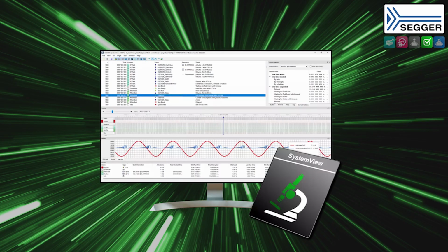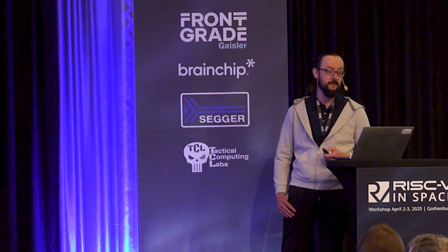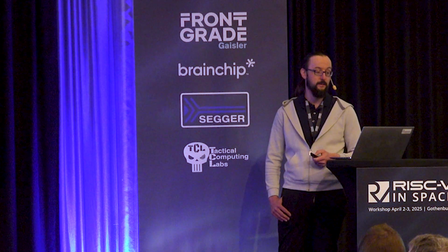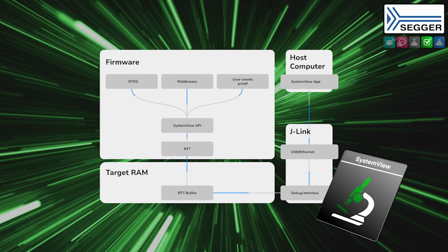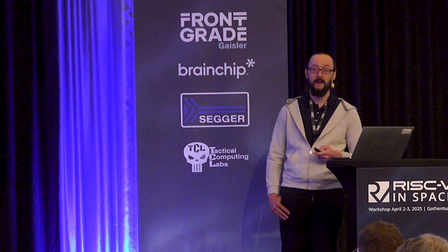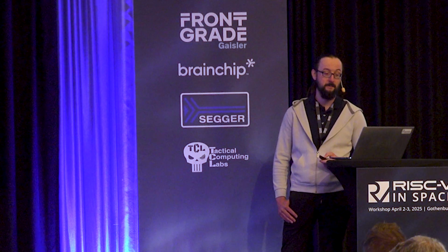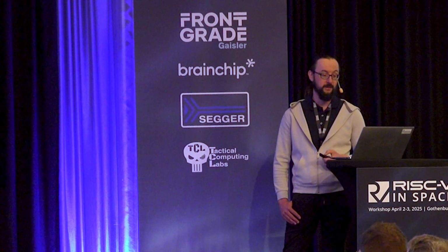Last but not least, the most powerful tool we get with system bus access and RTT is SystemView, a real-time recording and visualization tool to analyze and profile the behavior of embedded software. It's ideal for complex systems with multiple threads, tasks, and interrupts, and provides insights into runtime performance. SystemView works by instrumentation of an underlying RTOS and the application of the firmware itself. It generates events to provide a system-level trace and records it via RTT. With J-Link, we can capture the events, analyze and visualize them, updating live, all while the target system is running.